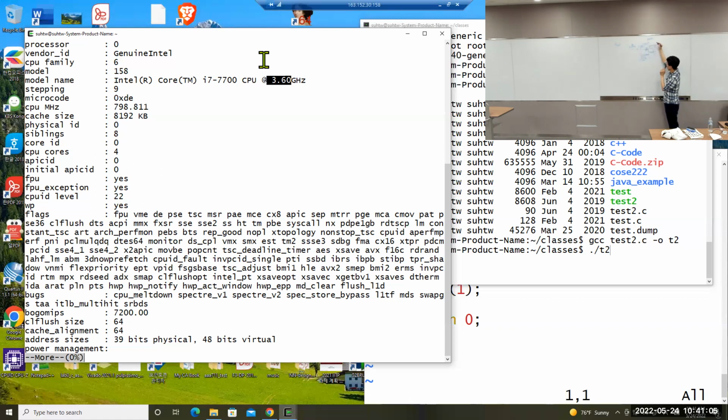Intel is using different terminology. It uses instruction pointer, IP, instead of program counter. ARM uses PC. In the Cortex A9, we have the register file R0 to R15, and R15 is the program counter, which is also 32-bit. From this program counter, an address is generated. This address comes out from the program counter to read the instruction, for instruction fetch.